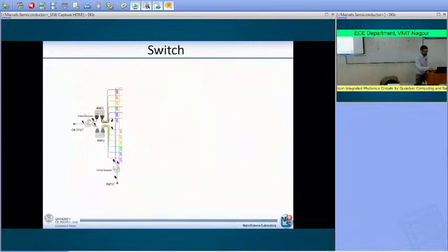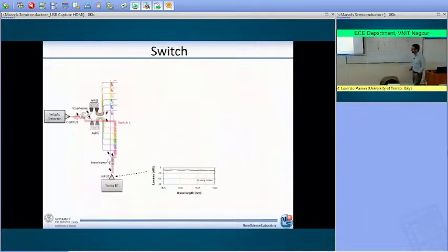So you start. You connect your laser to the input, you tune the wavelength, and you try to address the switching of this color to the output. And then you start to do the measurements. The first measurement is the grating coupler. You measure the amount of light that is transmitted into the circuit, the photonic integrated circuit. What you see here is the measurement of the grating loss over the wavelength region that you are interested in. You see that the grating loss is quite flat.